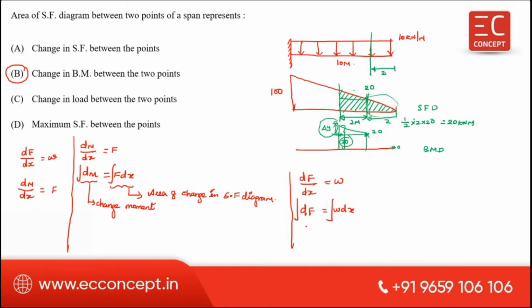So we can write the change in shear force between 2 points is equal to the area of W into dx, the loading diagram.